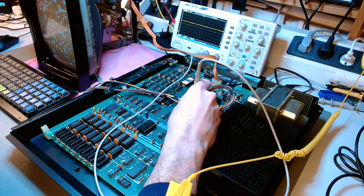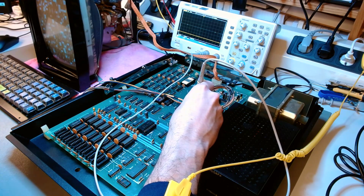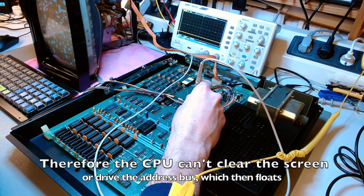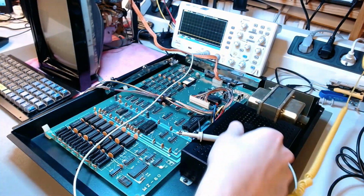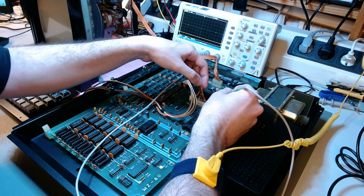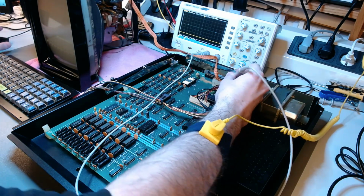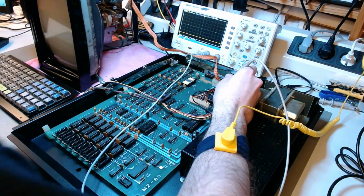M1, that's the instruction fetch cycle. The next one is reset. Reset is low, so the CPU is always being reset. That's a problem. The CPU is always in reset mode, and therefore the buses will float. So there are two sources of the reset signal. One of them is IC4 here, that's a 7414, which is an inverter, and output 12, if it is 0, it will become an active reset.